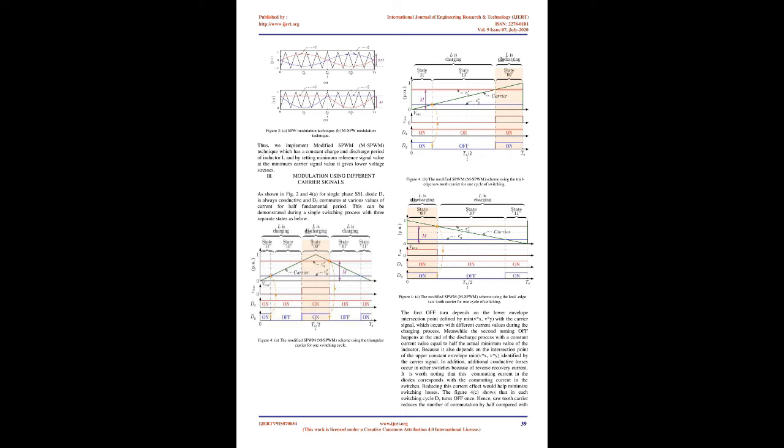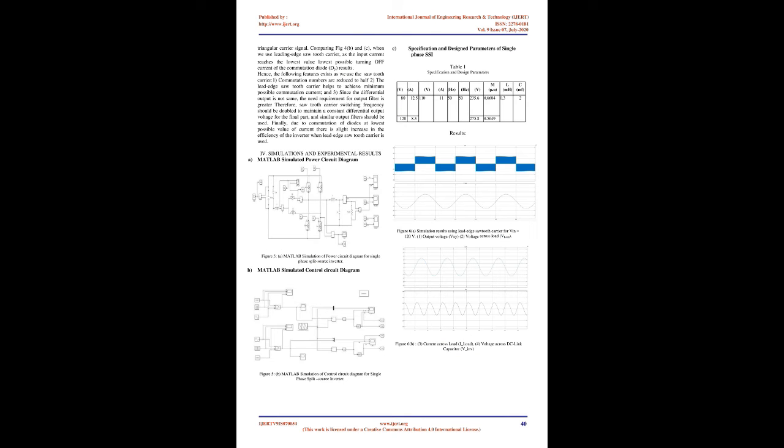Using the standard sine pulse width modulation, SPWM, technique, the above switching states can be achieved as shown in Fig. 3. Inductor L charges when the carrier signal is higher than the envelope specified by max(Vx, Vy). If the carrier signal is lower than the envelope specified by max(Vx, Vy), inductor L discharges into C through anti-parallel diodes of the lower leg. Because the envelope specified by max(Vx, Vy) oscillates continuously, this results in charging and discharging of inductor L with oscillating duty cycle. Therefore, there is an increase in the low frequencies at the DC side voltage and current. Also, it increases the voltage stress across the switches.